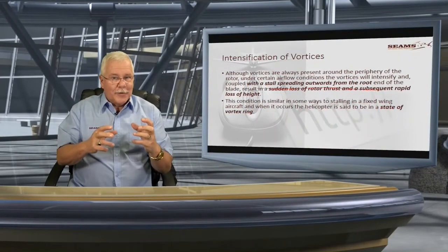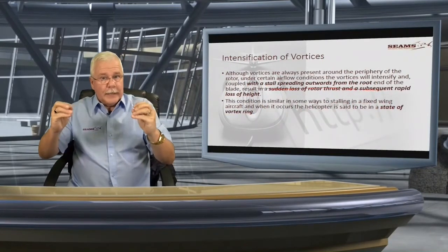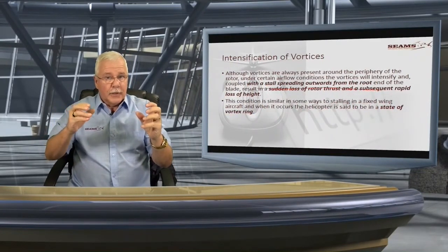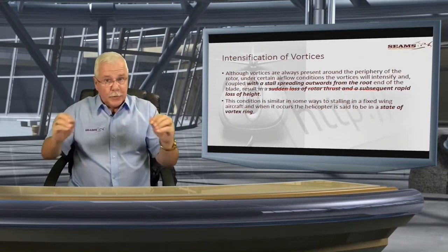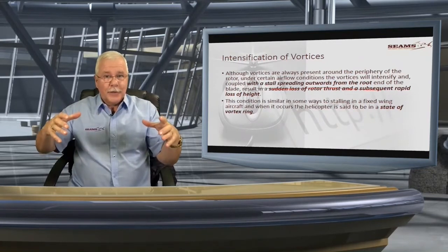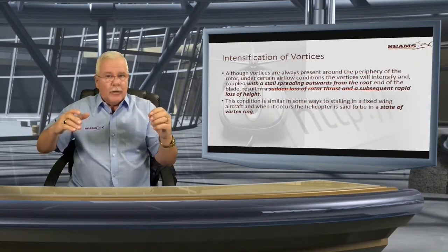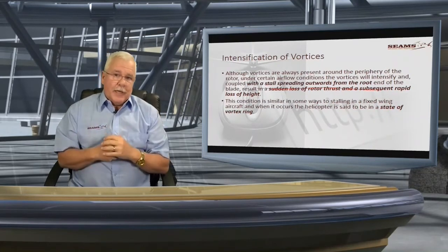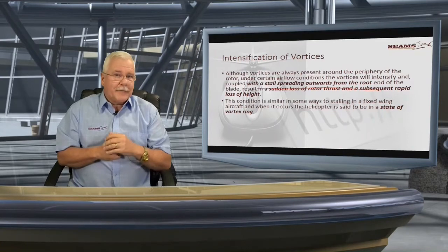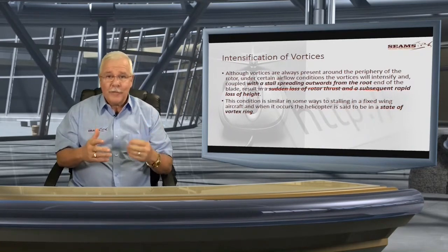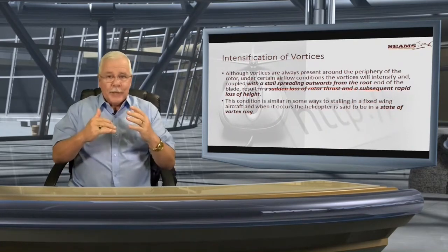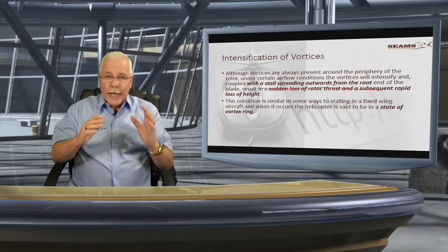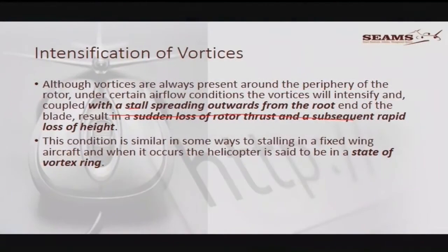Now I think the penny must start dropping. The wing is stalled. How many blades? They stalled. The disc now can be solidly stalled, or stalled in a sufficient way that it's not capable of maintaining the weight of the helicopter. Obviously, if there's any positive G maneuvers involved, then the power required is more, the thrust or the lift required is more, and so on and so forth.